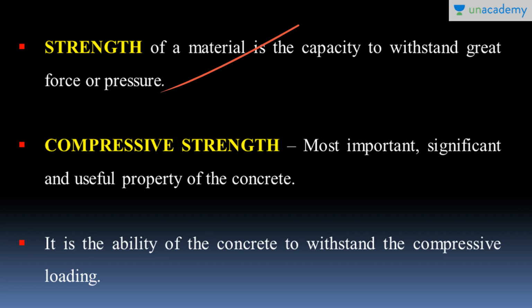Okay, that means to withstand a great intense pressure, to withstand a great crunch situation, it can be said as strength. Okay, so in case of concrete, when we refer to strength, it will be mostly the compressive strength of the concrete, because concrete has been designed in such a way that it takes the compressive force, or lets the compressive force pass through it to the next elements, and finally to the ground. Okay, and to the substructures and to the ground. So once more, when we talk about the strength of the concrete, most probably and generally it indicates the compressive strength of the concrete.